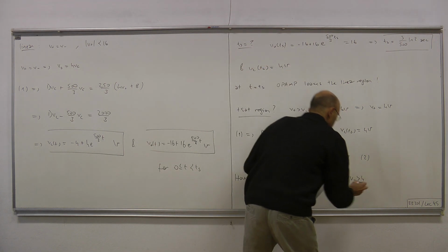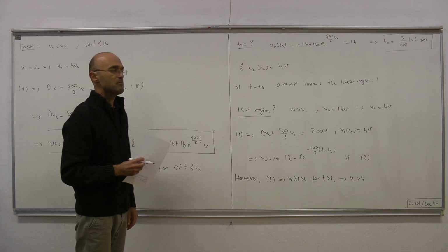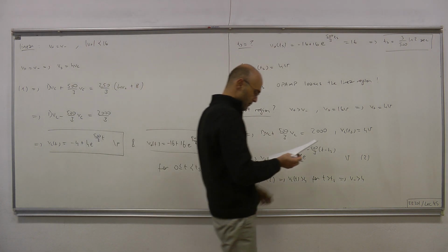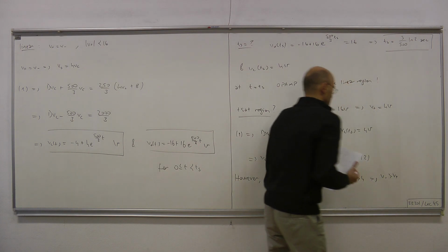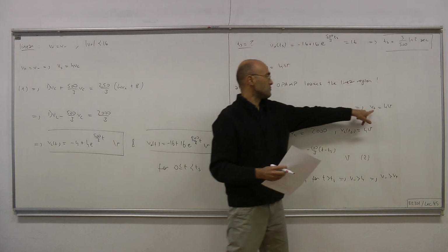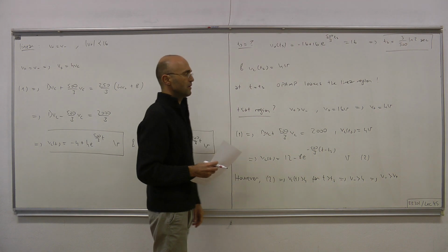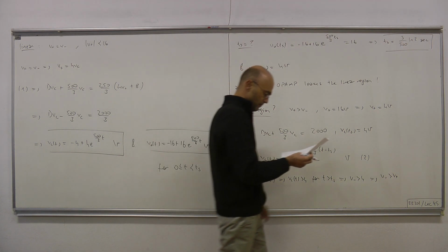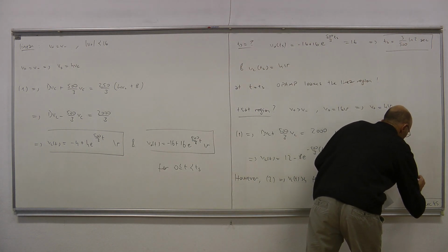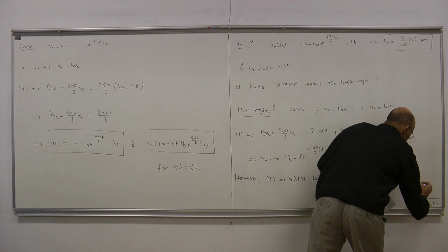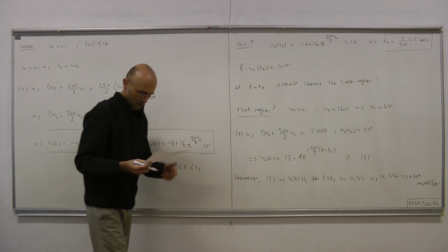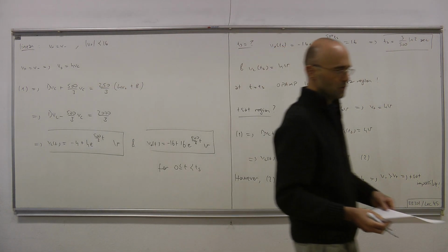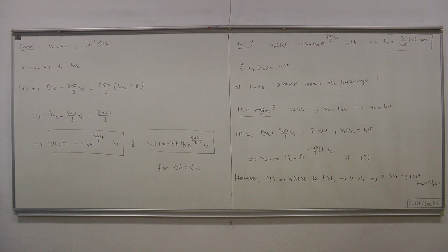Since VC is V minus, and it is greater than 4, that means V minus is greater than V plus, because V plus is fixed at 4 volts in the positive saturation region. And positive saturation is not possible. So let's go to the negative saturation region, therefore.